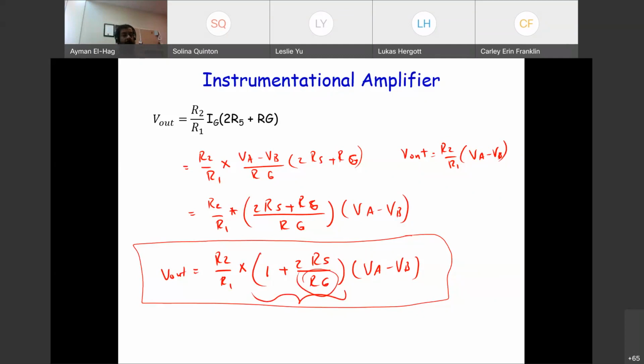It will have no noise or less noise because of the differential part in the circuit. Second, it will have high input impedance, which isn't available in the differential amplifier, but is available in the op-amp. Remember, the op-amp has a high input impedance itself, but the differential amplifier does not because of the branch we needed to connect to make it. Third, I have control over the gain.